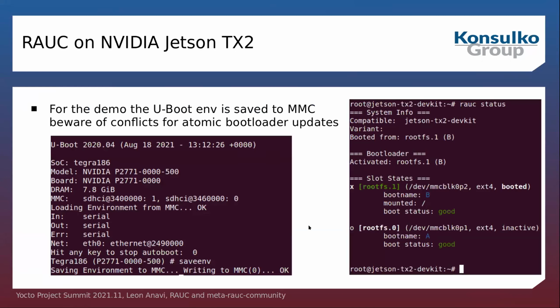Just to mention that this is just a demo, and for the demonstration, the U-boot environment is saved to the MMC, as you can see here. This is a screenshot from U-boot captured over a UART to USB cable. So if you are interested in using this approach for updating NVIDIA Jetson TX2, including the bootloader, beware that there might be conflicts because the U-boot environment is saved to the eMMC.